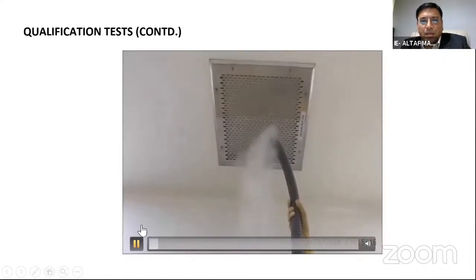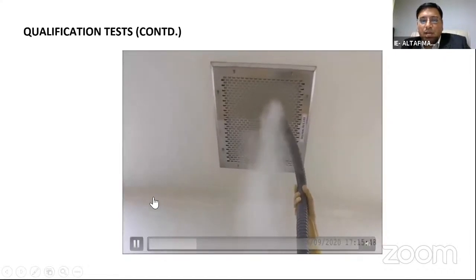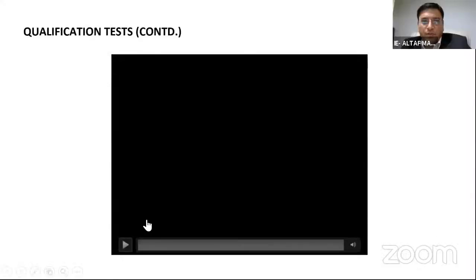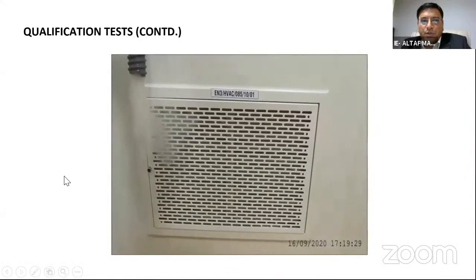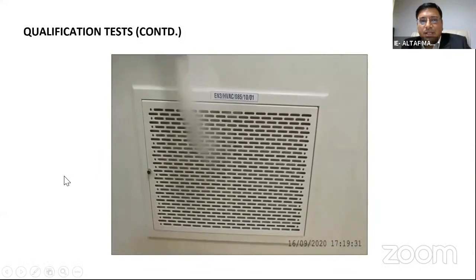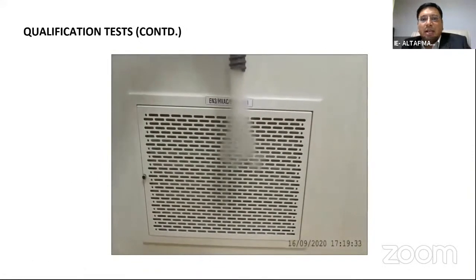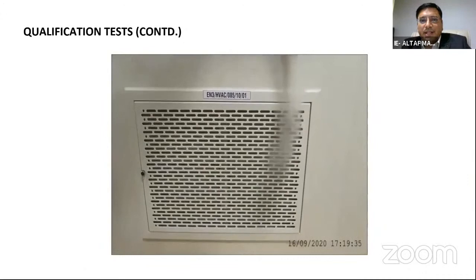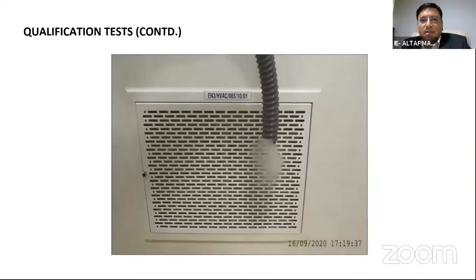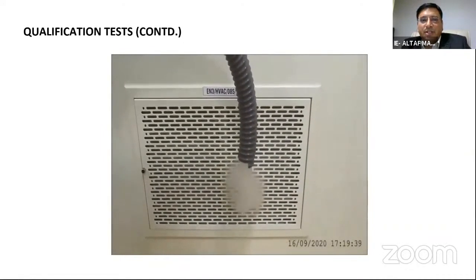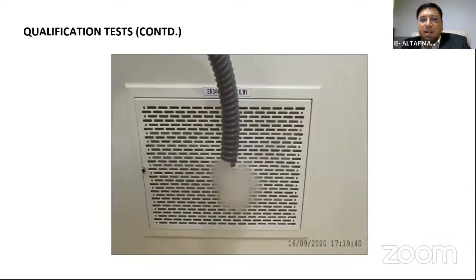Another video we have is showing you the AHU blow. One more video we have is showing you the risers. This is a riser, low level return, and you can see that air is going inside the riser. These are the smoke pattern tests, which are generally conducted at the end when all validations are done, with room numbers marked, grid numbers marked, and supply grills marked.